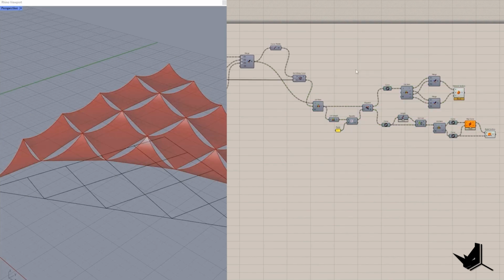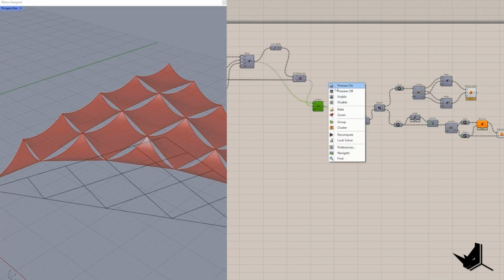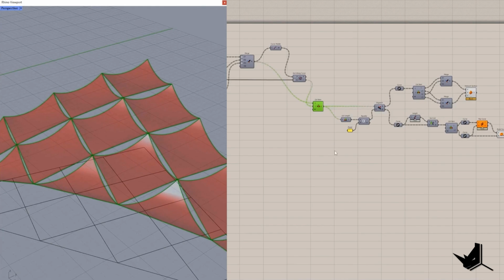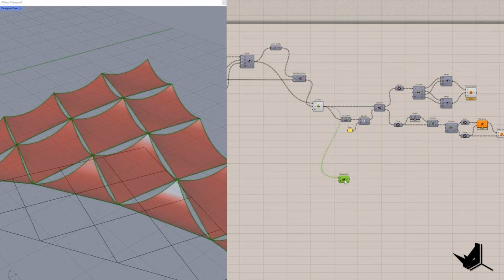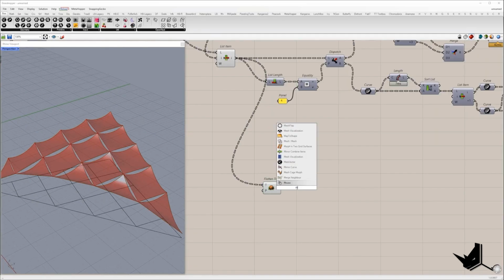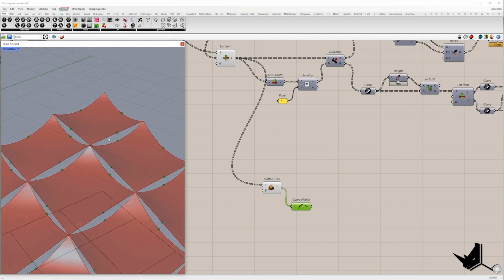So for that, I will go back here and I'm going to take the segments and I will flatten them. I will place in the same list all these curves. Then I'm going to find middle point of each and I will say, okay, take each point and find me 2 closest point from this curve.